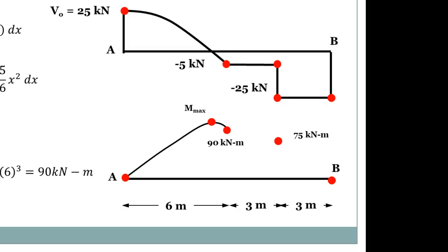This is the shape or concavity. Then, looking at the shear diagram, the segment I'm talking about has a zero slope, so if I integrate it, it will have x to the first power, so it has an inclined line with a slope, which is this line, and again for the other segment it should have another slope.